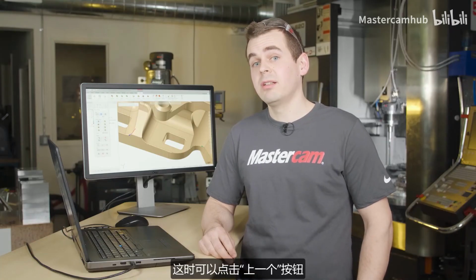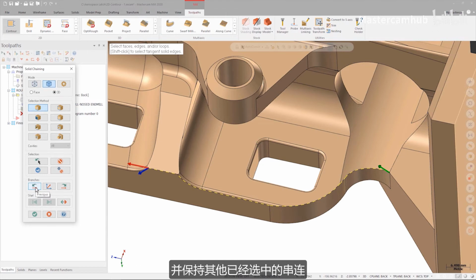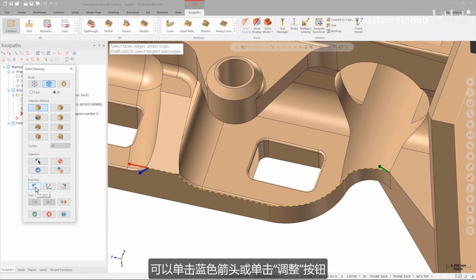As I advance around the part, there may be areas where Mastercam follows a different route than I need. I can back up by clicking the previous button, which is new to Mastercam 2020. Clicking previous will back my selection up by 1 edge and leave the rest of my selected chain in place. When I'm back to the proper branch location, I can either click the blue arrow or click the adjust button.